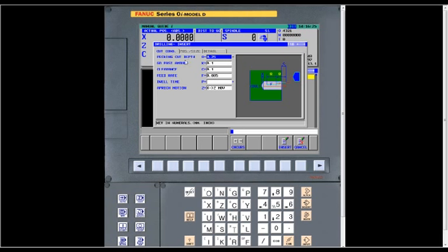So what it's asking for is pecking cut depth, and you can see it has Q highlighted. That's like if you're doing a G83 drill cycle where you want the drill to fully retract; it's asking for the amount of each peck. Then the go-past amount is just to allow for the angle on the drill. The clearance is like an R plane at the start of a drill cycle. Then your feed rate and dwell time, which again has an asterisk, so you do not have to answer it. That's like dwell time at the bottom of the hole. If you wanted it to dwell for part of a second, you could put that in.